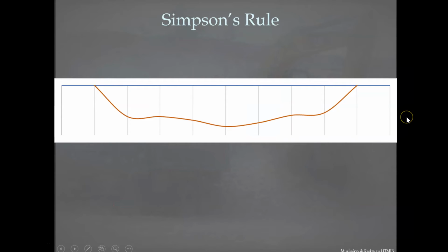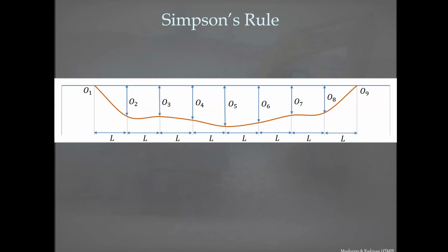If that is a figure again, now we're not going to make the approximation that the boundary line is straight, but we're going to fix it as it is. We're going to use Simpson, whereby we want to take the curvature of the boundary, and if the ordinates are still the same and the interval between the ordinates is still L,